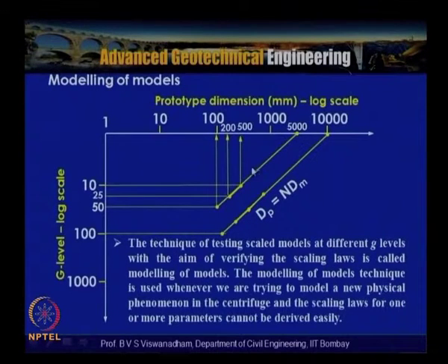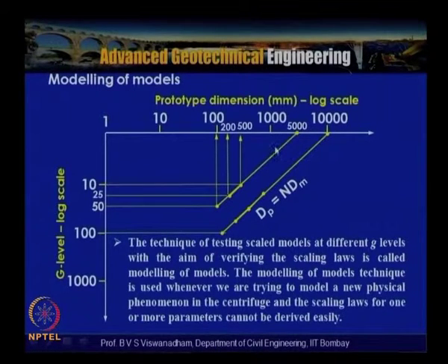representing the behavior. What this means is that if you have the same prototype with the same soil tested with identical boundary conditions, then the performance of the tested models, model 1, model 2, model 3, if they are models of this particular prototype, represents identical behavior to that in the prototype. So, this is an interesting option for centrifuge-based physical modelers for verifying the scaling laws, and also to check whether the models are free from particle size effects. In geo-environmental engineering, it checks whether it is free from the characteristic length effect.